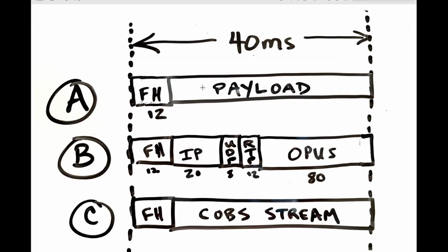And it gets a Viterbi code. That's right. So both are error corrected, with similar strength, but the frame header can be decoded by itself quickly because the Golay coder is pretty simple. So it gives you an advanced peek at the payload. If you had a high-Fidelity style architecture where the satellite was receiving many channels of this Opulent Voice modulation, then it might be able to get away with just peeking at the frame header.